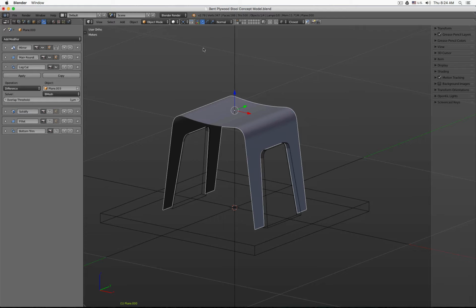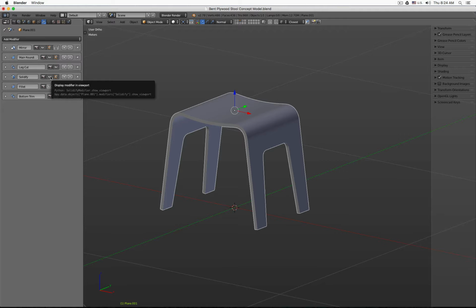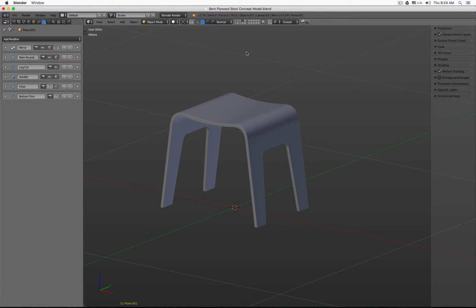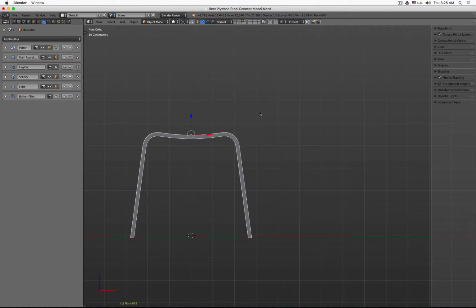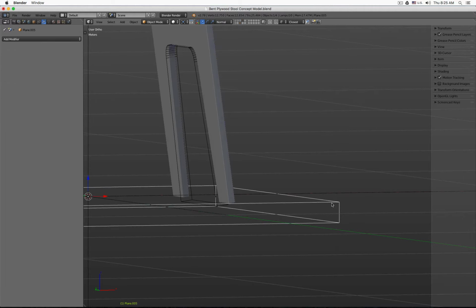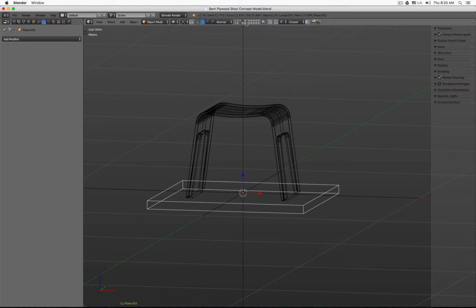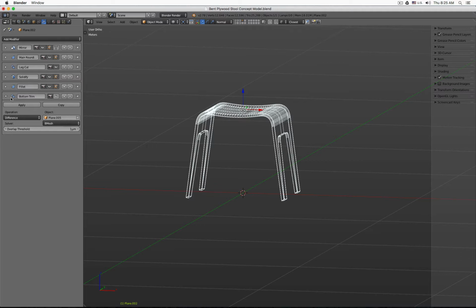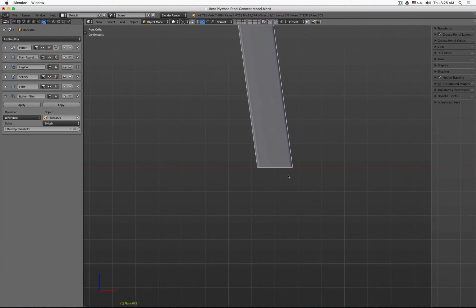And then this surface, you can see, I simply can add the solidify modifier to give it a thickness, and then for example here on the last step I added the fillet for the rounding, and in addition I trimmed the bottom area. I overbuilt the bottom area a little bit, and I created a box at the bottom, and this box I will use via another Boolean modifier and Bmesh and difference to cut the bottom area off at the end.